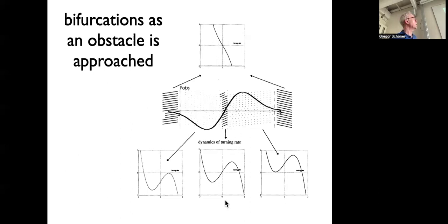If there is an obstacle close and we're heading exactly toward it, we want to have that decision: either go right or left, but don't go straight. If the obstacle is on one side and close enough, then we want an attractor at the appropriate side to turn away from that obstacle. And on the other side, we want to have the other attractor. That would be our phase diagram.